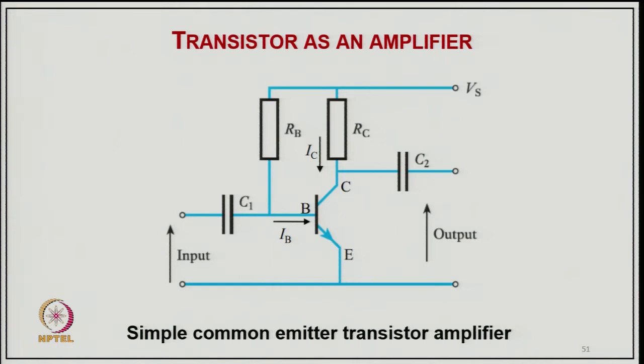You can just see here how we really work it out. We have an input AC, and we have coupling capacitors on both sides, with biasing from the supply voltage to the base, as well as a resistance between the line and the collector to limit the current when the transistor goes towards amplification.